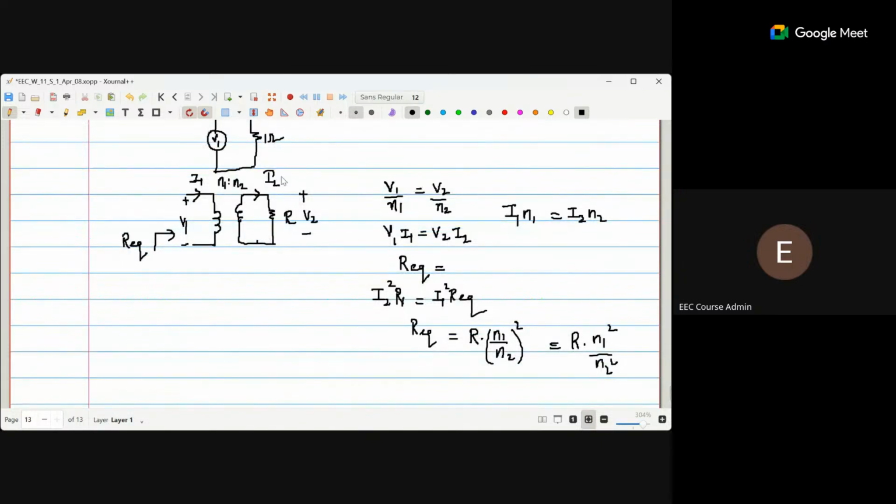And this is the basis behind the impedance matching between any succeeding functional blocks. I mean, if you connect two functional blocks, the output impedance of the first should match with the input impedance of the second block, right? So those things will be the fact behind this.